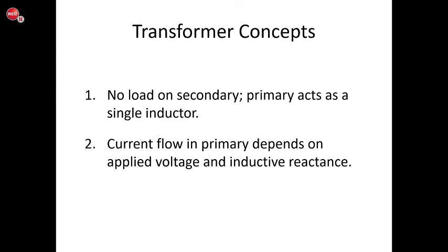Transformer concepts: no load on the secondary. If there is no load on the secondary, the primary acts as a single inductor. So if the secondary circuit is left open and there's no load, the primary circuit operates just as if the secondary is not even there. There's no interaction between the magnetic fields from the secondary to the primary.